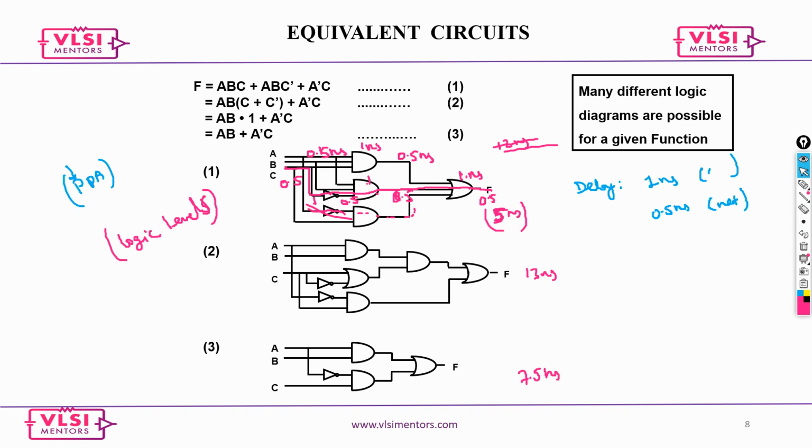Sorry, come again. Say for instance input A, B, C, all three are 0, 0, 0, and then all three are changing to one, zero to high. It doesn't matter. No, you cannot go with that kind of assumption. What matters is how much time. Your combinations can be anything. What matters is the maximum time the whole circuit takes to change at the output or give you a new output.